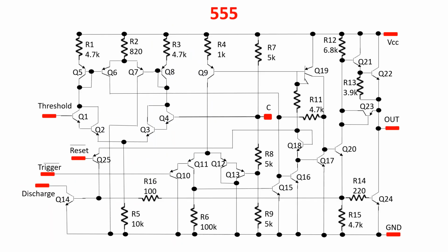Now let's finish the circuit analysis with the Camenzind words. There are several flaws in this design, indicative of the early period of the IC design. Neither comparator is well balanced, showing offsets of as much as 30 mV. The circuit can get away with that because the voltage swing is quite large. The operating currents are quite large. The lateral PNP transistors run at up to 1 mA. That was acceptable at the time since the device had 10 micrometers geometries. Today it would be excessive.